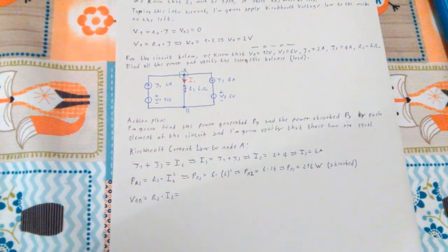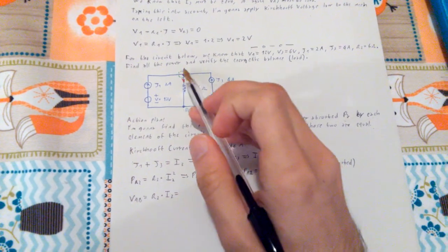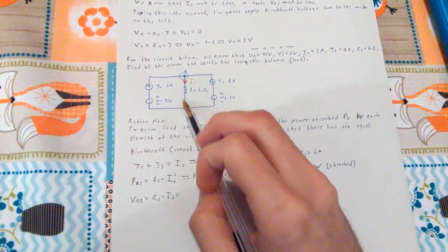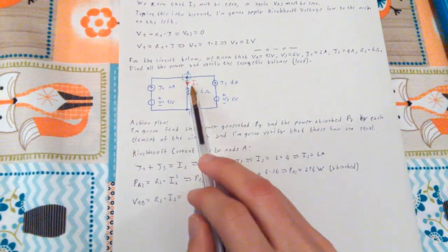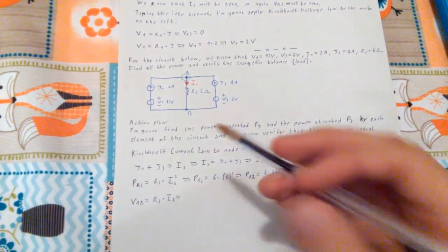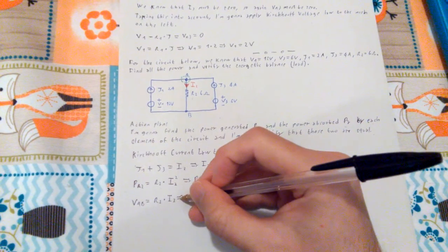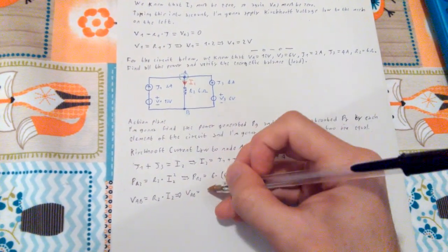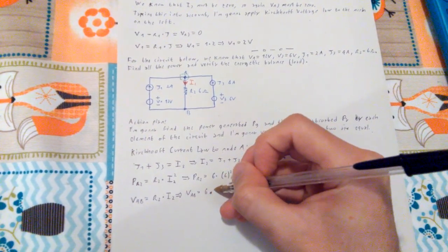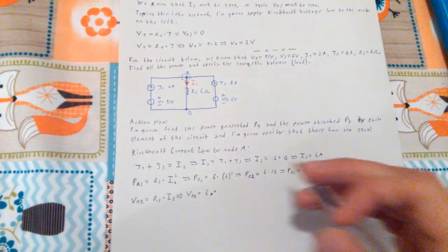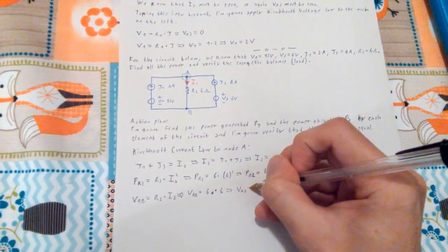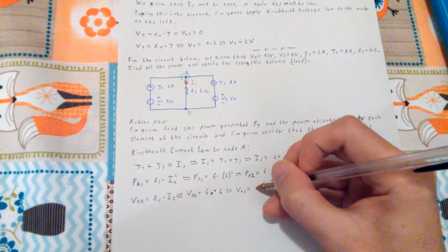Okay, makes sense. We have two ends, A and B. So the voltage here is going to be basically the resistance times the current, which I've just found. So if we plug numbers into this, we're going to have R2, which is 6 ohm, and we also have I2, which we just found is 6. So 6 times 6, VAB is going to be 36 volts.